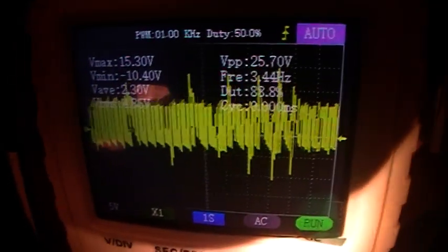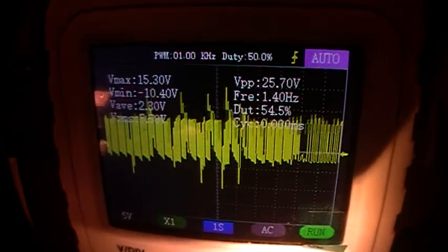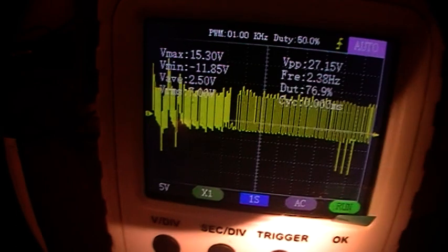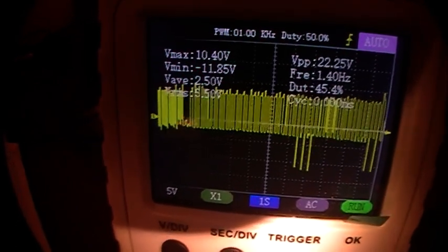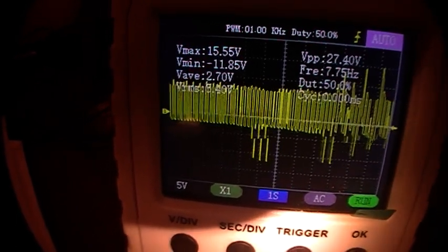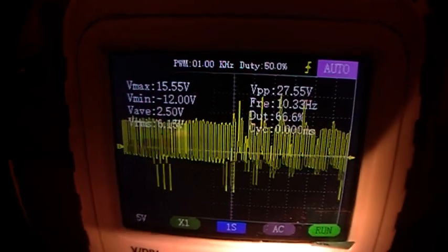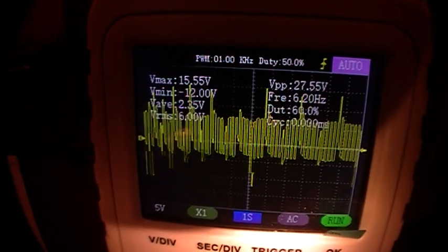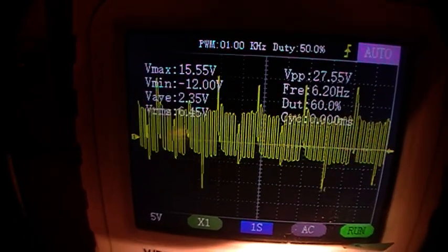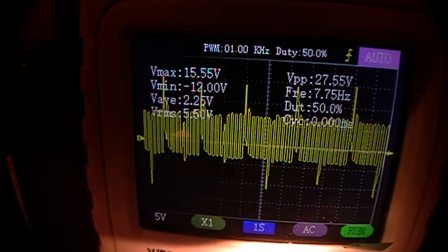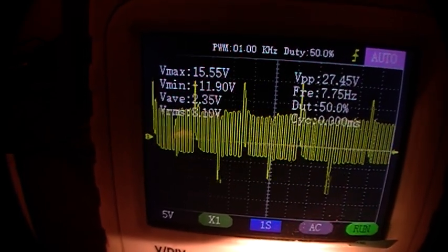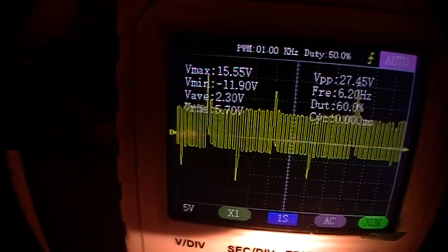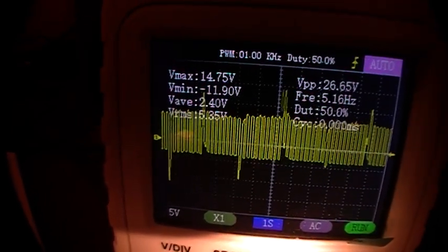Now I'm going to turn it right onto number 5. This is the last capacitor in the capacitor chain. That's a 10 microfarad capacitor. So that gives me the slow pulses now. Look at that, I'm turning the pulse adjust. Look at the frequencies on that. Okay, turn it right down to the slowest pulse rate.